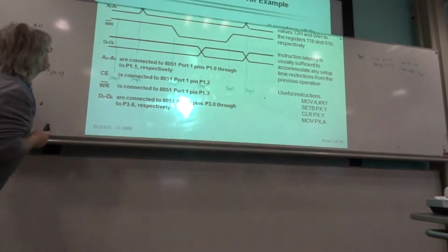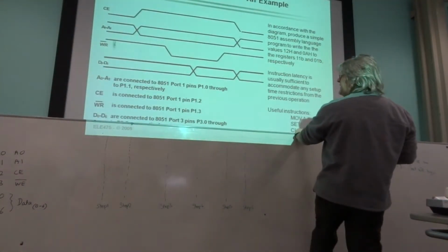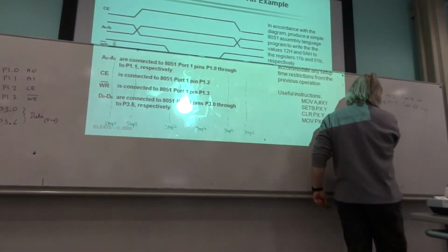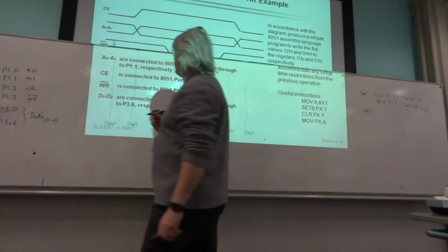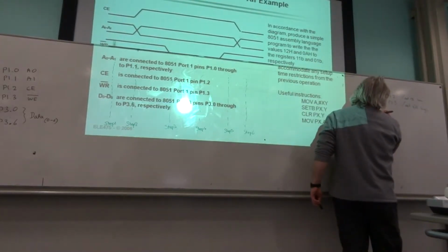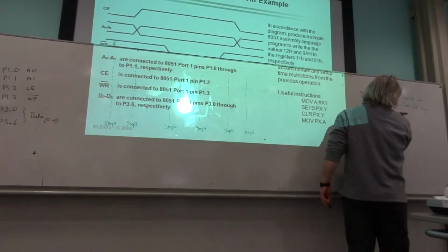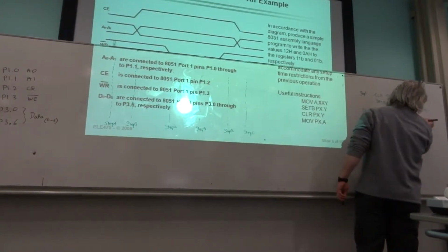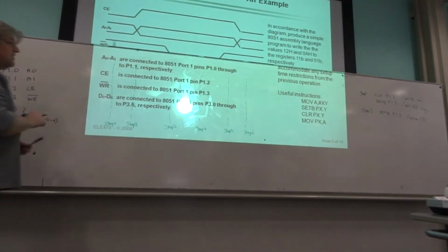So, didn't need to bring that all the way down, did I? So step two, I've got to make chip enable go high. Well, that's not difficult. So set B, P12, raise CE. But I've got to do something else in step two. I've now got to put out the valid value on the address bus.